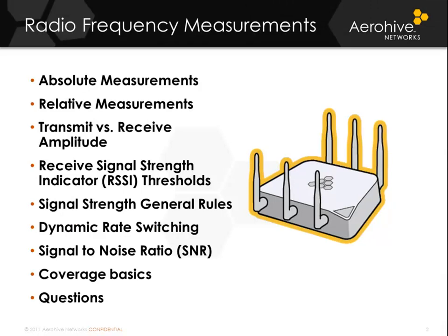In this session we will discuss absolute measurements, relative measurements, transmit versus receive amplitude, receive signal strength indicator thresholds, signal strength general rules, dynamic rate switching, signal to noise ratio, and coverage basics, hopefully answering a lot of questions you may have around these things.